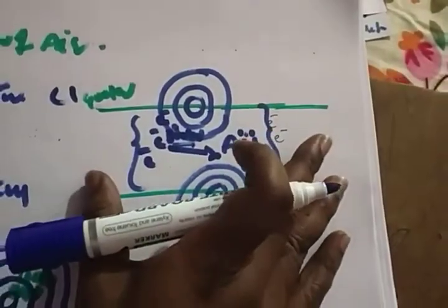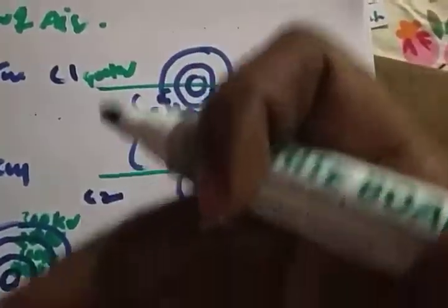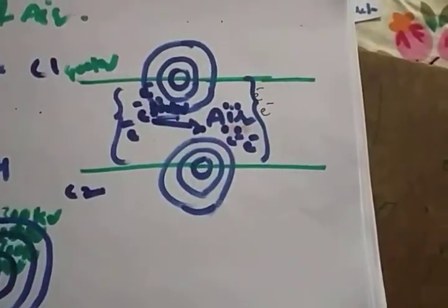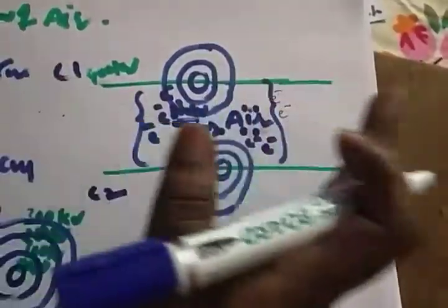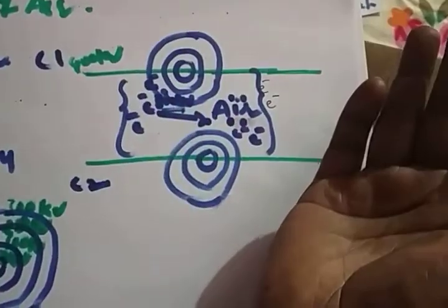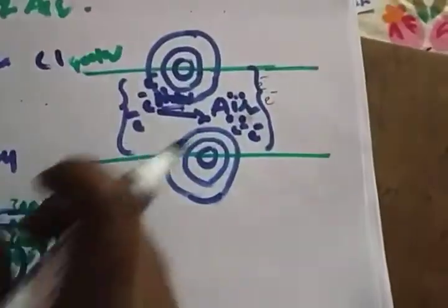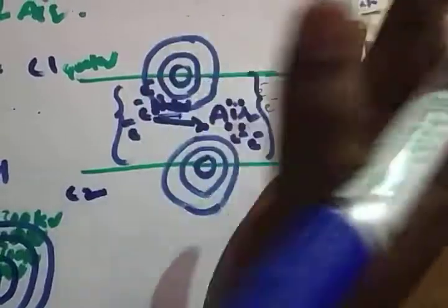So that hissing noise, when electrons flow from the top conductor to the bottom conductor, means the movement of electrons. Large voltage transferring means a large force on the electrons, and large numbers of electrons will hit the air molecules. Definitely the molecules will be divided and they will develop electrons and ions. Then electrons again hit the air molecules and develop more electrons. Like this, the space between the two conductors fills with electrons. That means air got ionized.